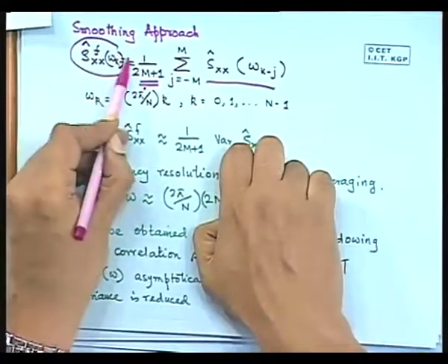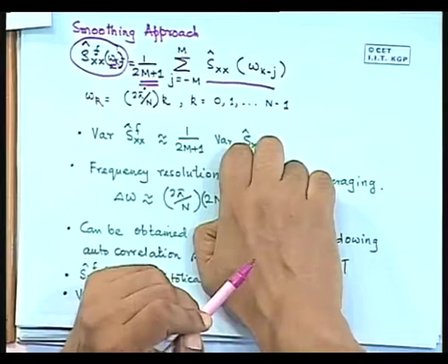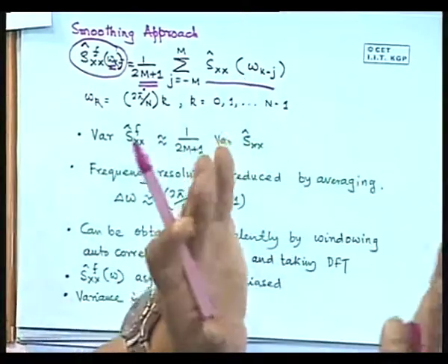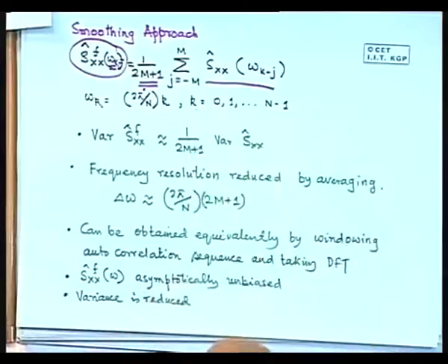from the same sequence. So what will happen is that now the smooth sequence at every point is actually a function of the old sequence over the last delta omega. So your frequency resolution is gone. You cannot catch the variations of frequencies over small frequency ranges because you are going to average them. So the curve will become smooth. So that is what you are sacrificing. You are sacrificing on your frequency resolution to get an estimate which will not vary over experiments.